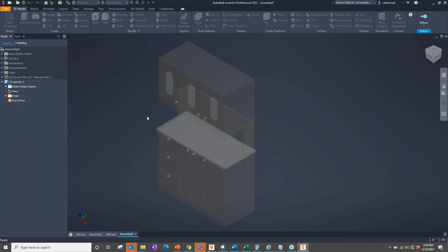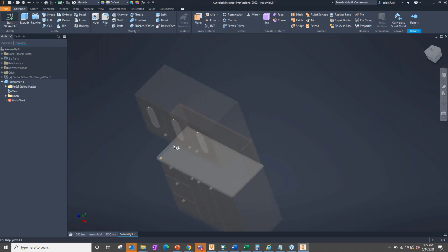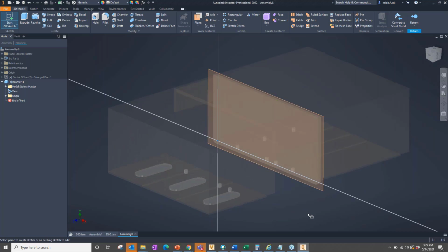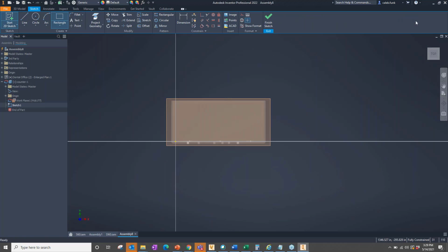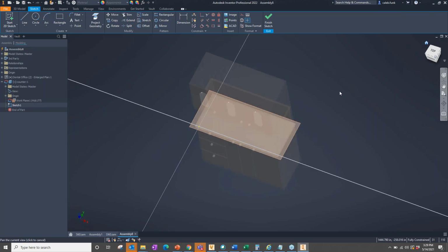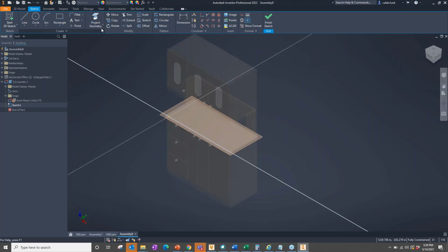And I'm creating it in context. So I've got my existing information from Revit right there. I have access to all of that. So when I begin sketching, when I begin working with this, I can use that just like I would any other geometry that I typically have within CAD.